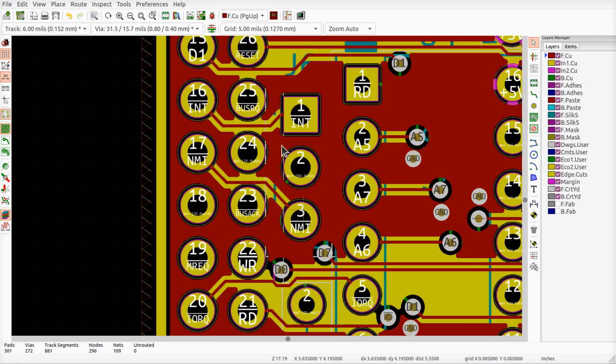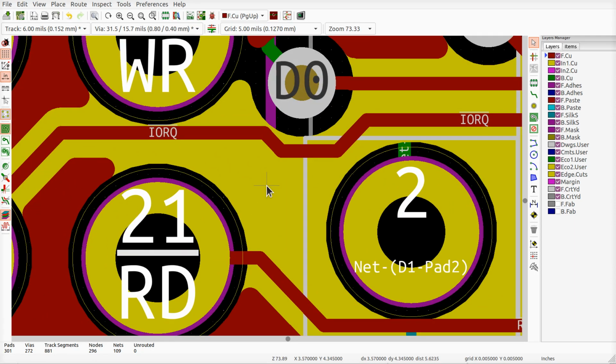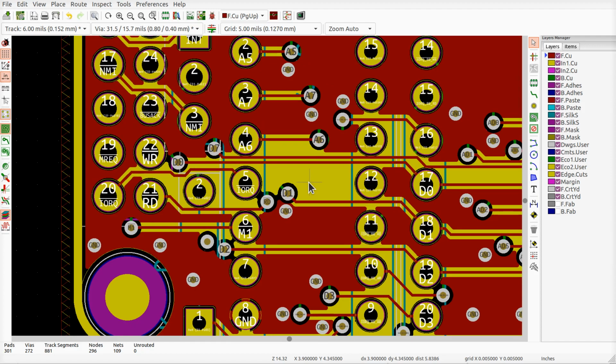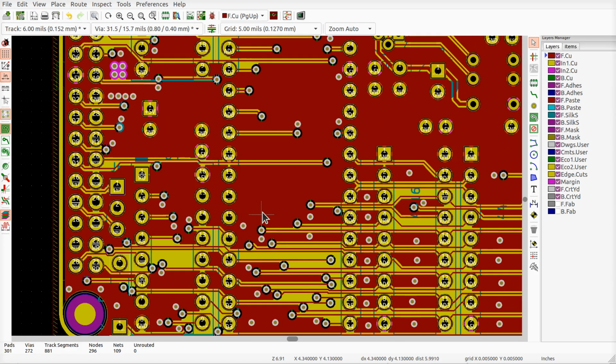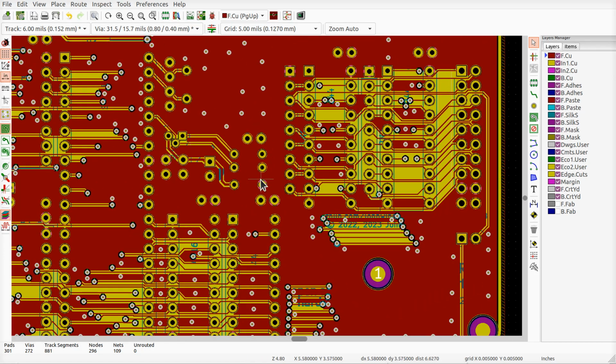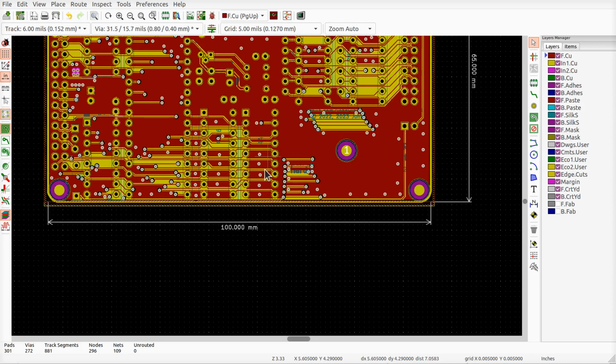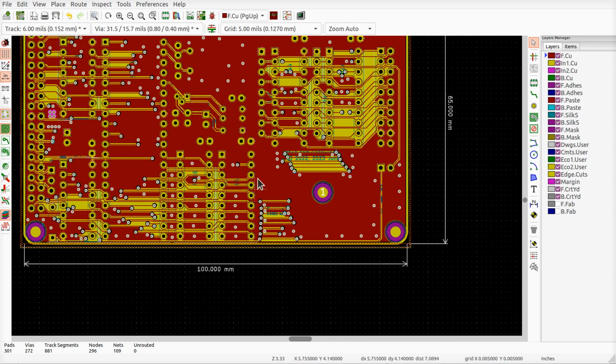Have an eyeball on the polygons. Now, I generally like to make sure that the polygons kind of fill up and consume a lot of the space in here. I don't think it's critically important that it does. Some other people have said that it's pointless to go ahead and have the ground fill on there. I mean, there were days of yesteryear where the board might curl up like a Pringles potato chip if you didn't have the same amount of copper on both sides.